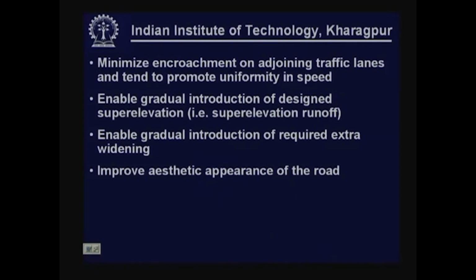Now, if we provide a transition curve, then that minimizes the possibility of encroachment on adjoining traffic lanes, and thereby tends to promote uniformity in speed.